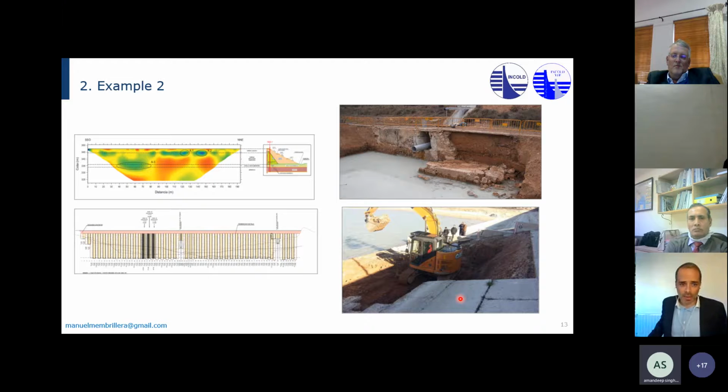And along with that, we carried out geophysics, upstream and downstream. This is downstream of the dam, and you can see these areas in the contact between these clays and marls and the foundation, areas where you can see that a lot of seepage is going on, because we have some galleries going through the dam body.